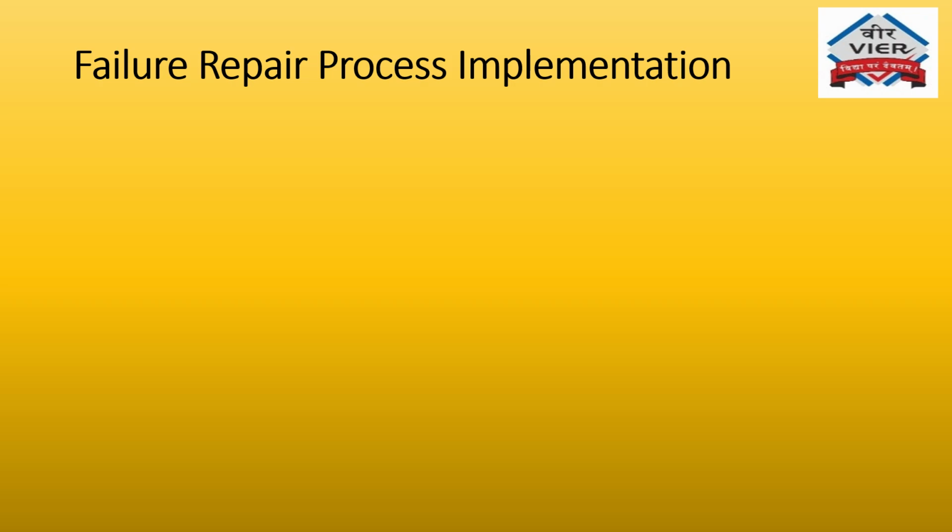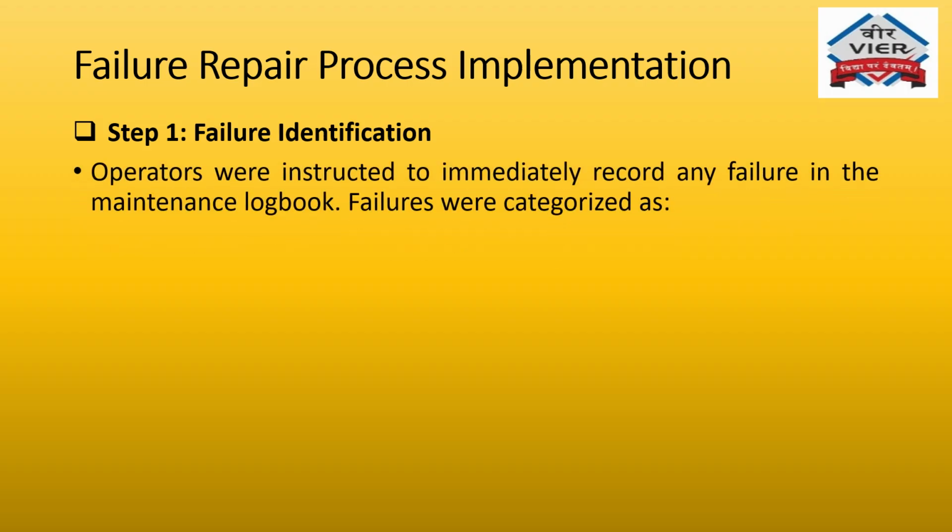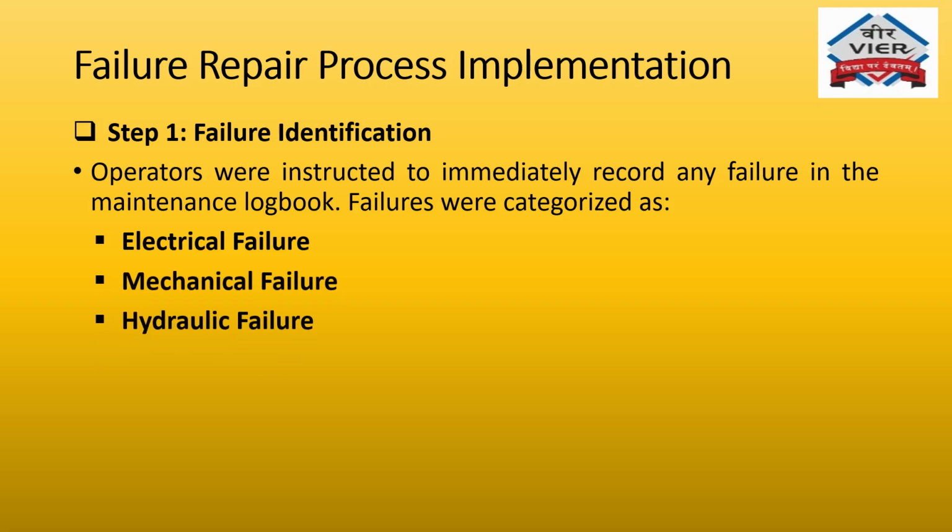So in the implementation stages, the first step is failure identification. Operators were instructed to immediately record any failure in the maintenance logbook. Failures were also categorized in terms of electrical failure, mechanical failure, hydraulic failure, and human error.